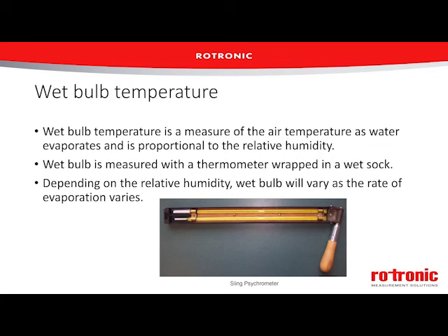And that's mixing ratio. And Michael, how about wet bulb? That's one of my favorites. Wet bulb temperature, again, we're talking about a temperature value, which is very different from our dew point or frost point values. The wet bulb temperature is giving us an indication of the cooling effect that evaporation has on a temperature sensor. So we see wet bulb being used on things like psychrometers, which we have a picture of here.